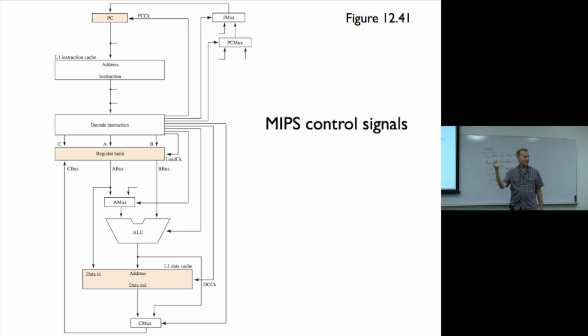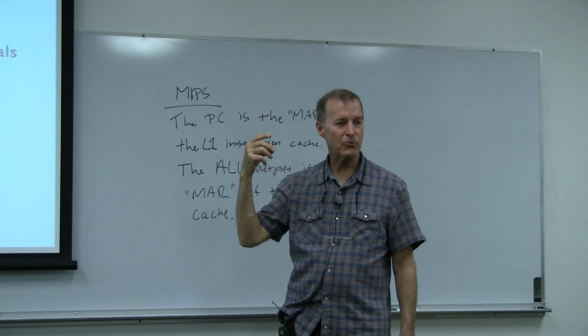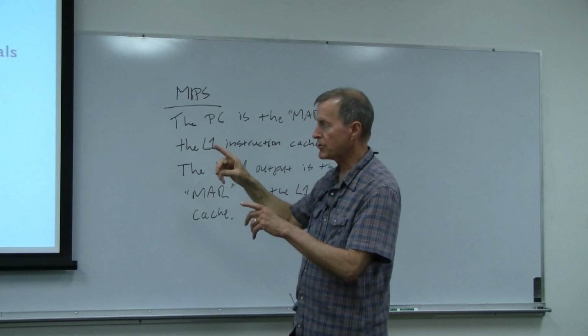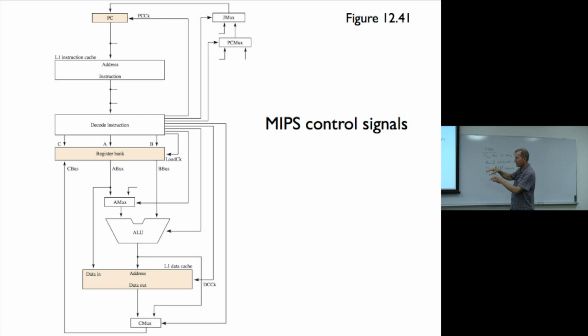So in one cycle, now think about what you said. In one cycle, or in one clock pulse, what changes with each clock pulse? What's in the data cache? Are you with me? What's in the register bank? Are you with me? And what's in the program counter? But that's all master-slave. So when that happens in one cycle, because the program counter changes, that might change what's presented to the register bank, but it's master-slave, so that feedback doesn't happen.